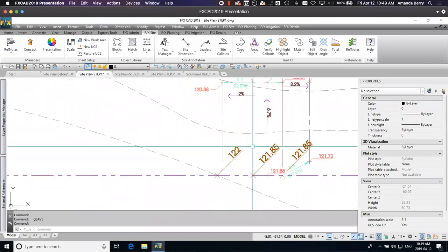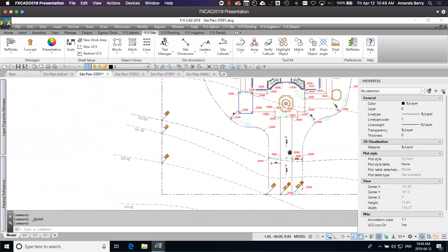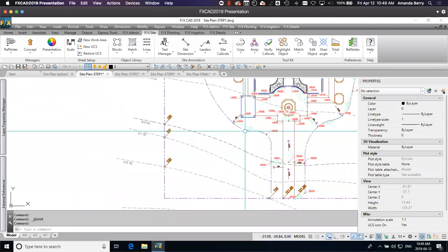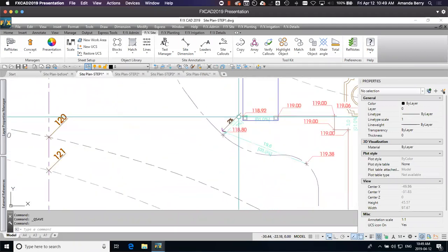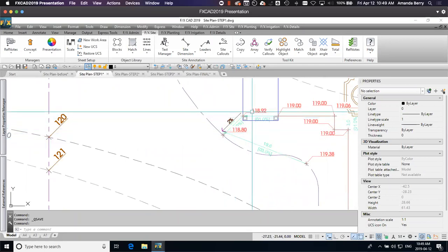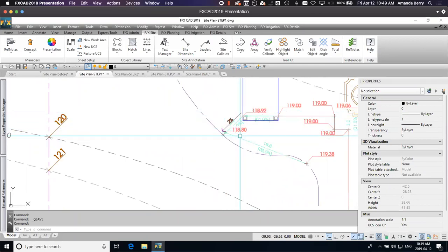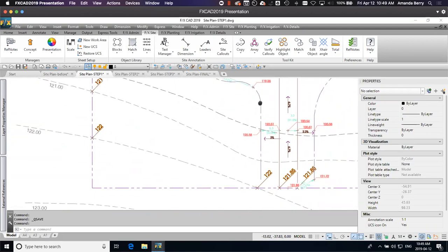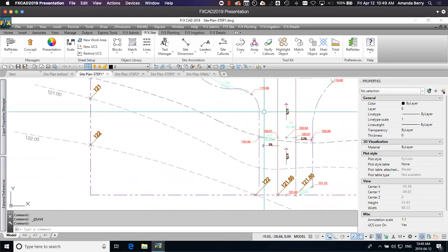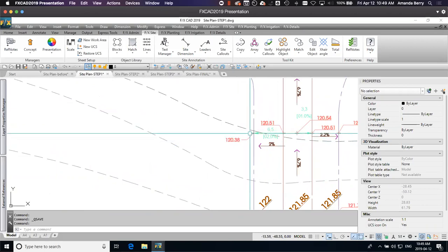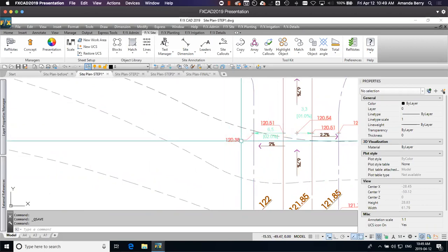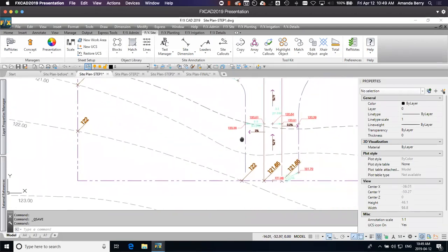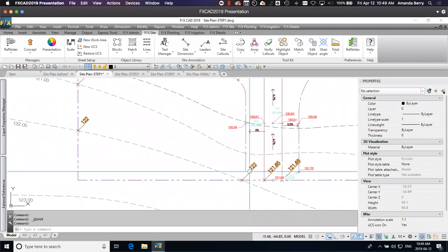is. So in this case, I want this swale to be at least 2% because it's on grass, so it drains positively. And I figured out one pinch point right here that for a 2% minimum, it needs to be at that point. So what I can actually do is I figured out at a 2% minimum, this point needs to be this. So now we just need to figure out what this is going to be.